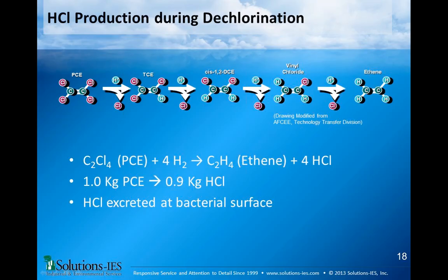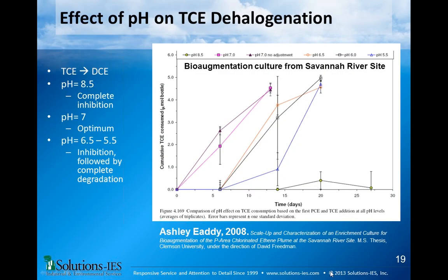I believe one of the things they did just to verify this, they went back and they actually injected the substrate directly into this zone here where they put the DNAPL, and they got a spike and an improved efficiency for at least a short period of time. In the field, if you knew exactly where you spilled your DNAPL and you could put a well there and inject into it, that might work. Unfortunately, we don't usually know where it is, so it proves their point, but I'm not sure if in practice you could do that.